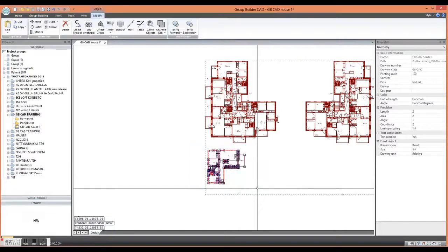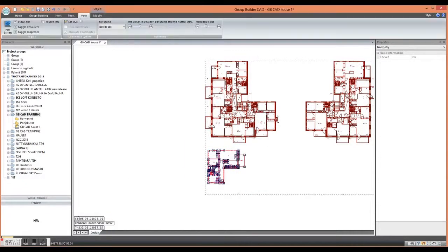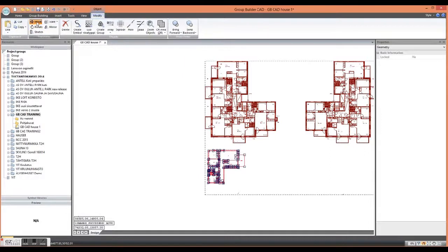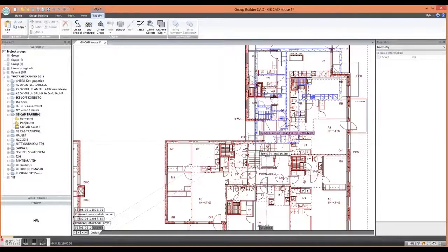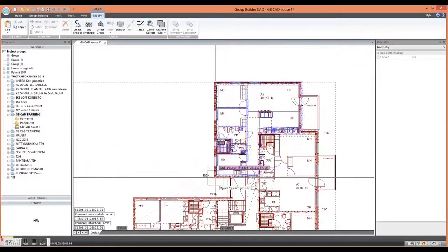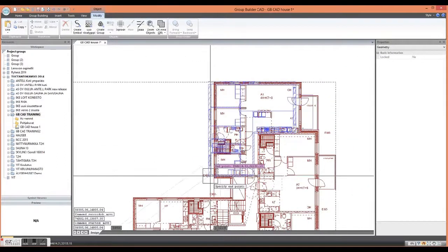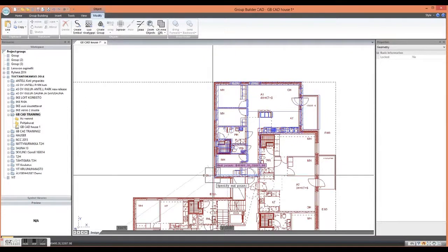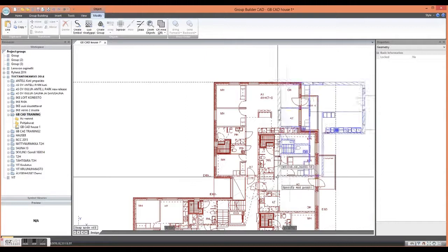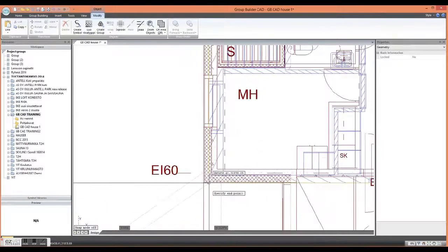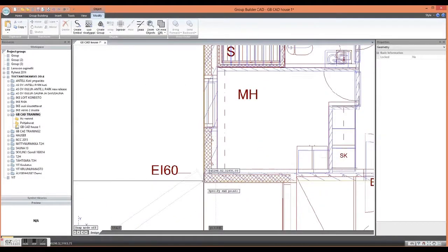So now I'll come from the left side, click modify, move, choose the corner of the file and move it on top of the DWG reference. Sometimes it's easier to insert the picture by unclicking the magnet, which will help you to draw the IFC model.